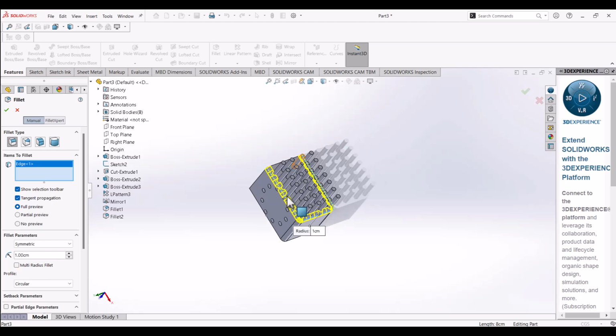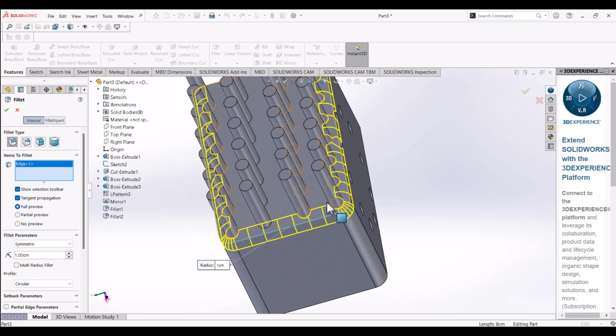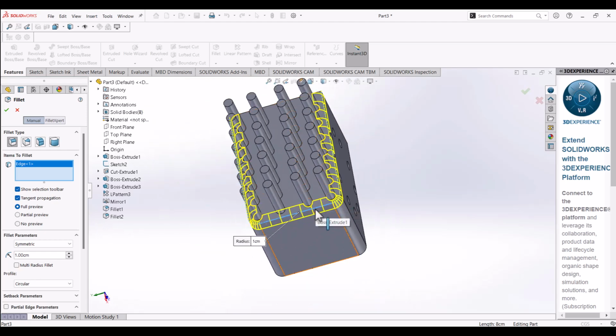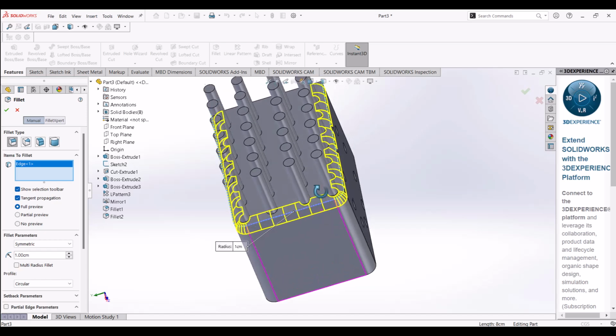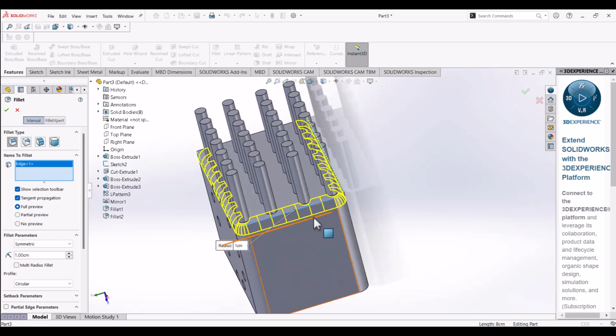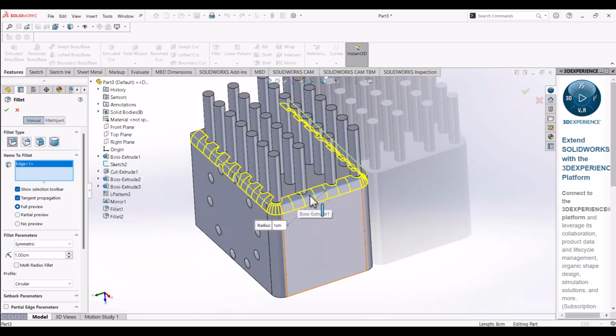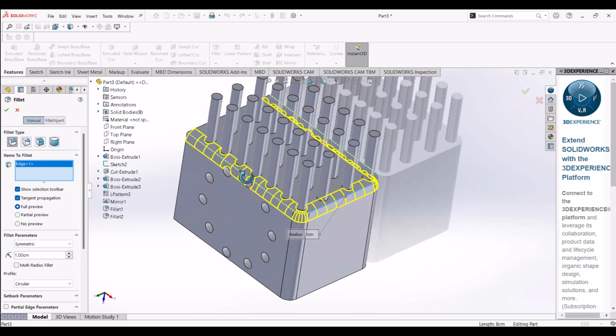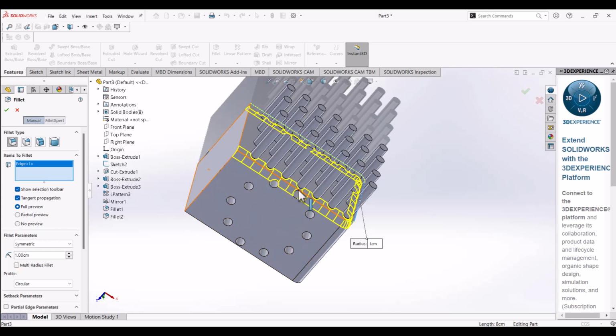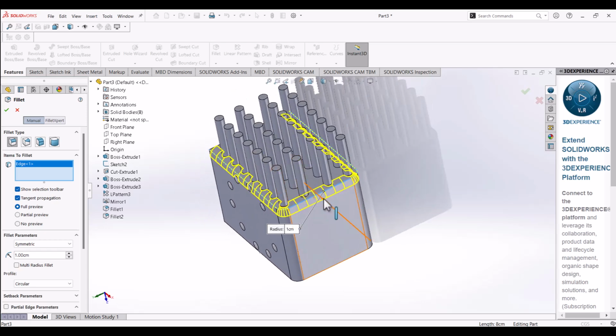This is how SolidWorks sometimes does it. Assuming you want one thing, the reason why it's selecting the whole surface is it has been programmed that once you select this surface, the pattern automatically picks a certain rhythm. It knows that once you've done the surface, you might want to create the other side, so it just picks it for you.